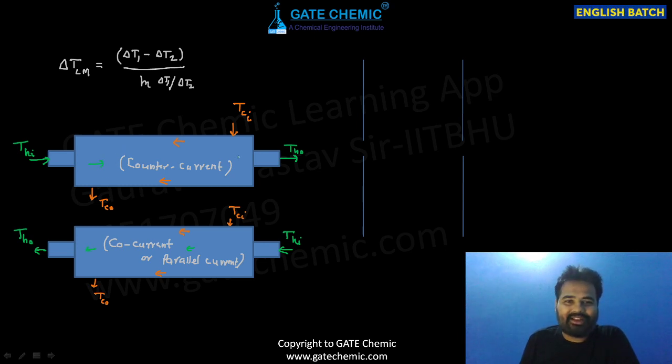See how interesting. Maybe in an interview it is asked whether we are going to do any special design for counter current pattern. No sir, we can use the same heat exchanger as a counter flow as well as co-current flow. We can use the same one in both ways.